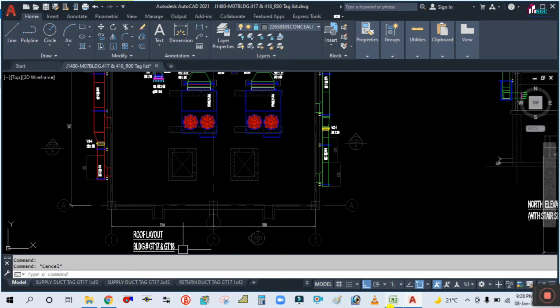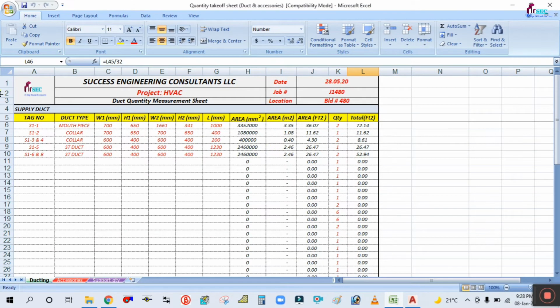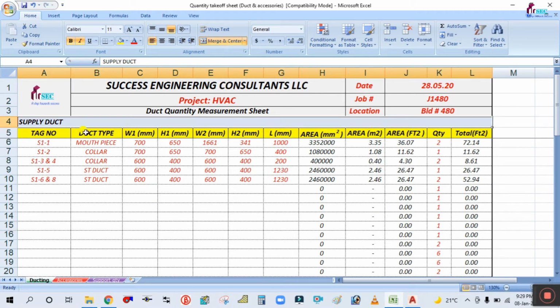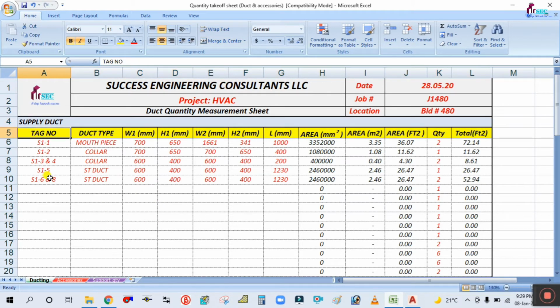For the quantity I have prepared one sheet. This is my channel name, Success Engineering Consultant. This is the project. You have to write the project here, then duct quantity measurement sheet, date, job number, location. This is for the supply duct. This has tag number, duct type, width 1, height 1, width 2, height 2.